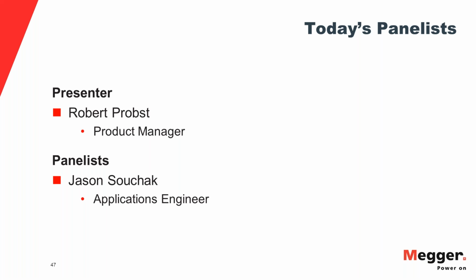The next question is, what is the difference between an acceptance test and an installation test? So fundamentally, it's the voltage that you apply to the cable, and an acceptance test is a bit higher voltage than an installation test, but it's also what you're looking for. Per the IEEE definitions of these, for an installation test, you're really looking for shipping damage more than anything. You're making sure that you get a good piece of cable onto the construction site, intact, and that you're not going to waste your time and energy pulling in cable that's already failed.